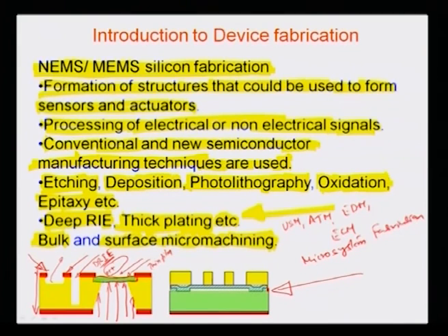So, here for example, this is a polysilicon layer which has been put in a manner so that you had a sacrificial layer in this particular region given by the dots. It could be a resist layer, and then you have deposited the polysilicon layer on the top of this resist layer, and then later on you can remove the resist layer away, because polysilicon is a high strength material, so that you can have a channel on the surface on one side and buried within this polysilicon layer on another side.